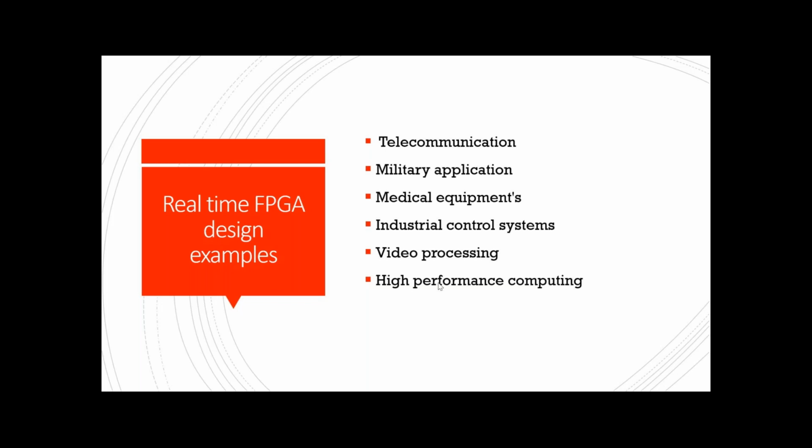So what they do in that FPGA core, if they want to implement some configurable functionality, is put that configurable functionality into a small core. We call that an eFPGA. In the sense, even the processor itself can have an FPGA: a fixed ASIC with a small FPGA inside. Whatever algorithm we want to put in that is going to be upgraded or updated over a period of time, we'll put in the small eFPGA, so that in the future they can upgrade the way they want. That is also a very interesting field.